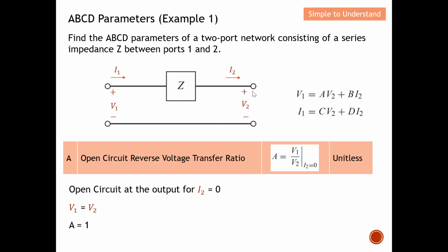So how can I continue this? Imagine this Z here as a resistor, just to analyze this more easily. When there's a resistor here, I can determine from this situation that I2 is equal to 0. Therefore, I conclude that V1 is equal to V2, because there is no I2, and when there's no I2, V1 is equal to V2.